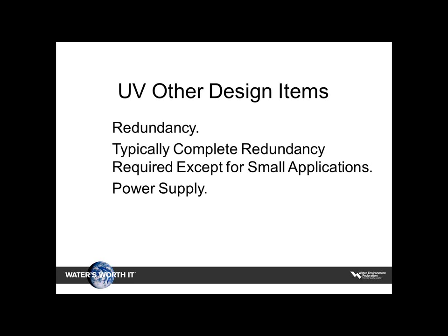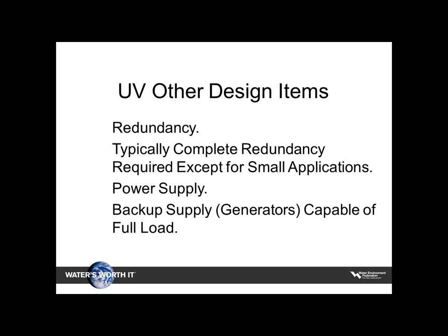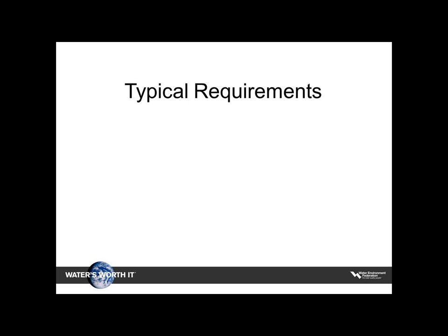That doesn't really fly. Particularly on a retrofit, this may be a consideration: do you have enough standby power to run the UV disinfection system if you have to run on standby power? Again, for backup supply, you need to reiterate full load, and when I'm talking about full load, I'm talking about the full load of the disinfection system. That would be, at a minimum, from a regulatory standpoint, one thing we would definitely be looking at.